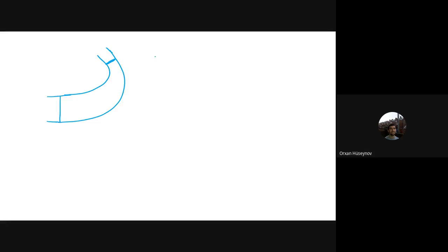And then the net forces acting on the system, the CV in y direction. So we are looking now at the y components of it. That one will be equal to m dot v out in y direction minus m dot v in in y direction.